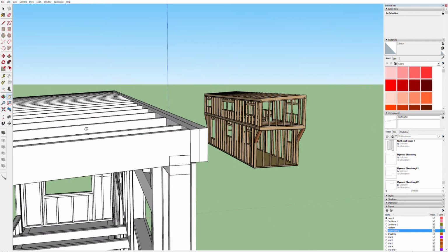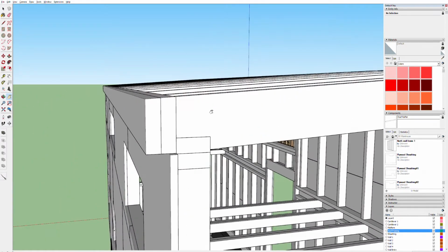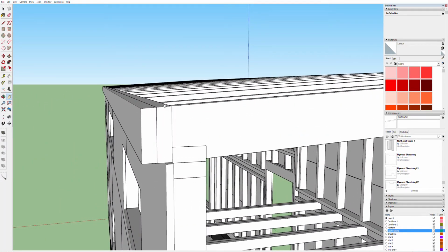On the bottom side, same thing: sheathing, water barrier, and then we're going to have a piece of flashing first over here, which is going to do the same thing I just described. And then we're going to have the roofing on top of that. The water that comes down the roof is going to be like shingled because the drip edge is underneath the roofing. It'll shed off the roofing onto the drip edge and then off and away from the house, hopefully clearing the house completely. So that is the idea for that.